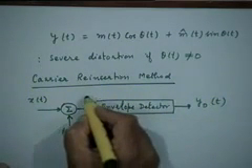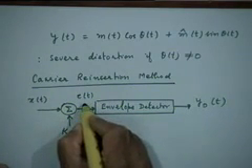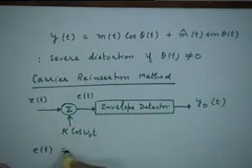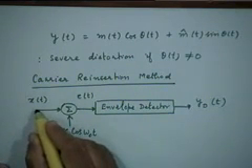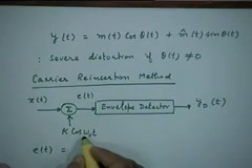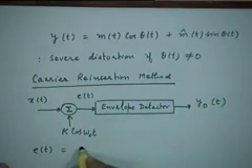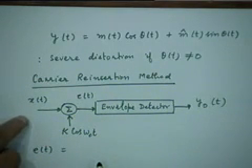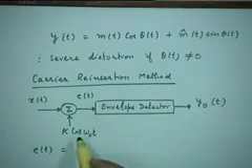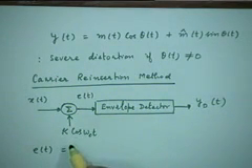To see what happens, let us consider the signal e(t) at the output of this adder. What does it look like? It contains the SSB signal coming in plus the local carrier, right? If you remember, x(t) is m(t) cosine omega ct plus m hat (t) sin omega ct, right? And you also have k cosine omega ct added to that. So the cosine omega ct has two parts now.